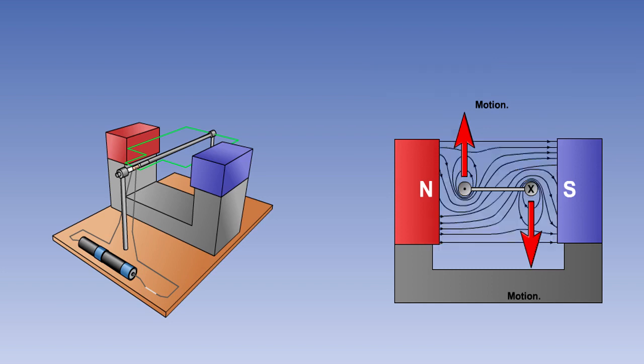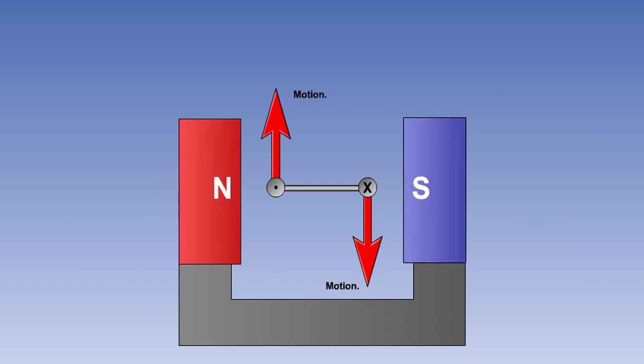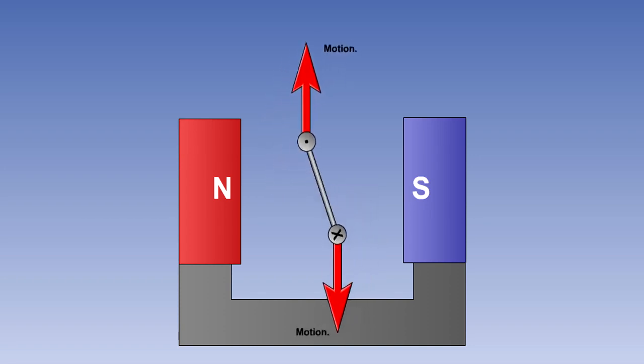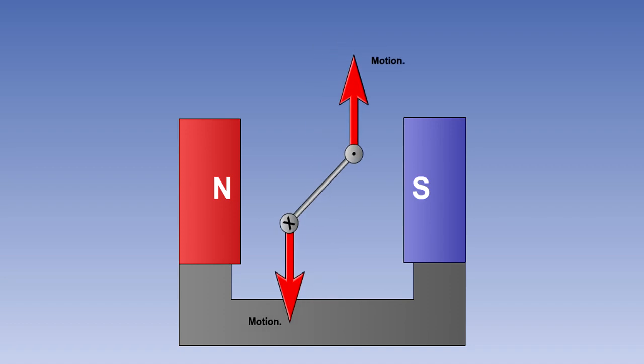Notice the shape of the magnetic field around the wires. If you imagine the magnetic field lines to be rubber bands under tension, the wires of the loop are about to be catapulted in the directions that we have just predicted using Fleming's left-hand rule. The resultant forces produced by the interaction between the magnetic field in the loop and the field of the permanent magnet will turn the loop around in a clockwise direction.